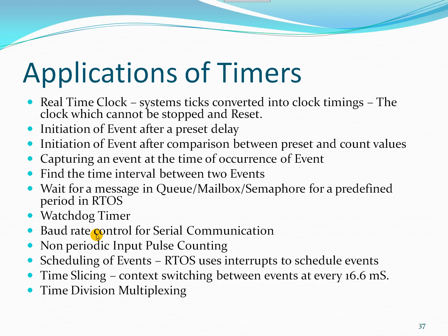If the message is not received, then that process will be forced into sleep mode, or that process can be deleted also. For those kinds of operations, the RTOS will need these timer applications. So this is one of the applications in RTOS based on timers.